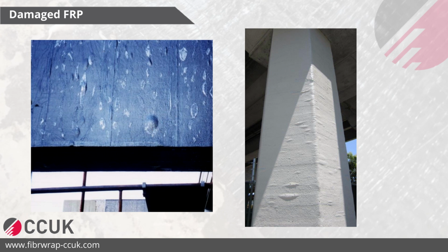That is called amine blush in the epoxy. That happens when you apply epoxy in a very low temperature. So it reacts and becomes a very different color. So that tells you clearly that it was not applied in the correct environment.